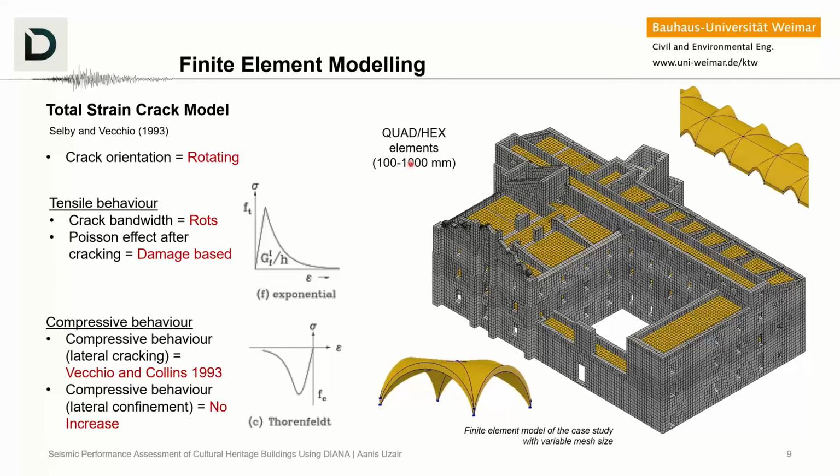But because most of the time we want to run something really quick, and we do not want to have a very detailed mesh, then the reliability of the results can be a good estimate of how fine this mesh should be. So the time that it takes and the detail of the results that you want determines how refined this mesh should be.